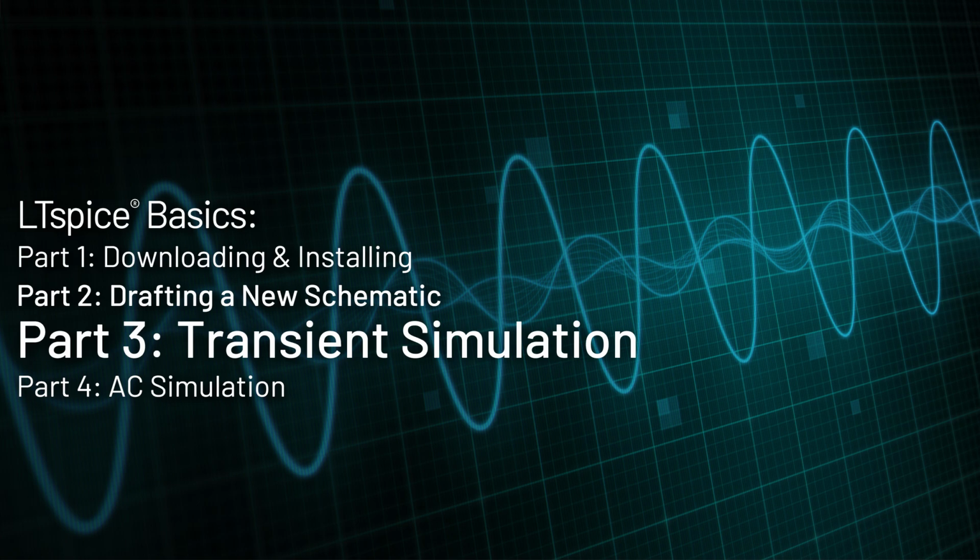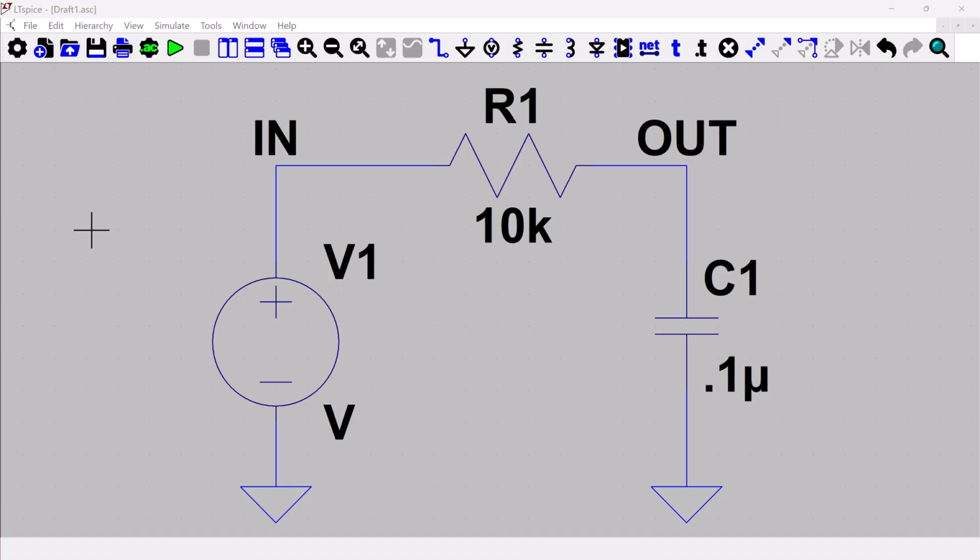In the last video, I showed how to create a new schematic from scratch. We're going to continue and now use this schematic that we created to run a transient simulation. So the two things that you need to do for a transient simulation is, first of all, you're going to need some sort of source, and then you're going to need the transient simulation directive.